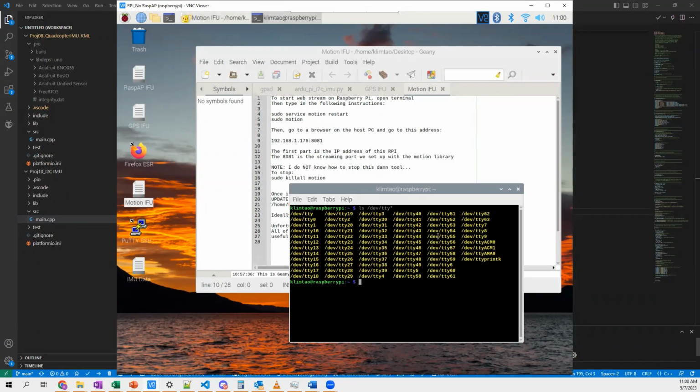And so the first thing I'll do, I'll probably mostly start from scratch here. I just, before the video started, did this ls dev tty check to see that my components are connected to the Raspberry Pi. ACM0 should be the GPS module, and ACM1 should be our Arduino that is hooked up so that I can communicate over PuTTY.